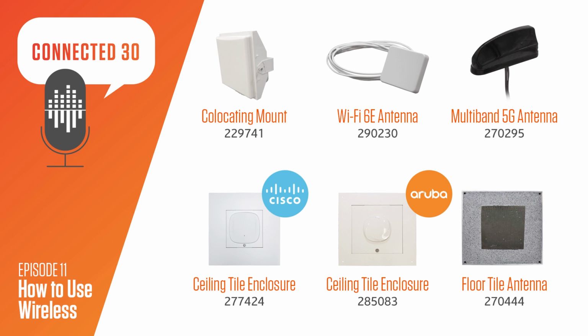Now, to the point where we're talking specifically about current Wi-Fi 6E access points with internal antennas, we've actually come out with a new raised access floor design, which we call our RF-friendly floor tile. It's a raised floor tile using a concrete raised floor panel, where we've cut out some of the steel on the back side of the floor tile, where we have what we'll call RF-friendly windows, where there's no metal and there are actual windows cut into it, so that we can transmit and receive through the concrete.